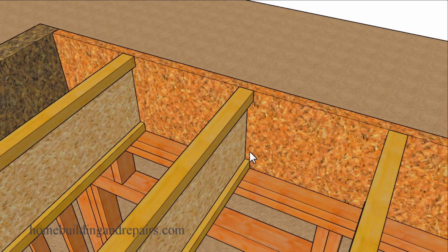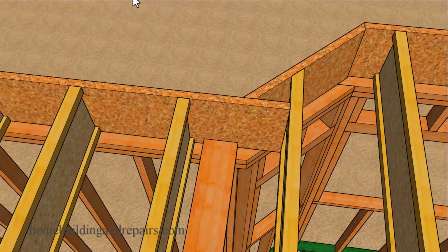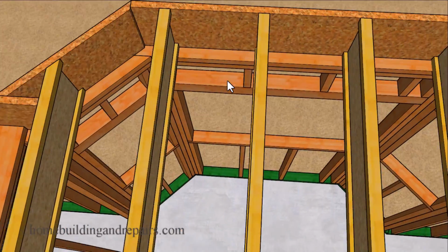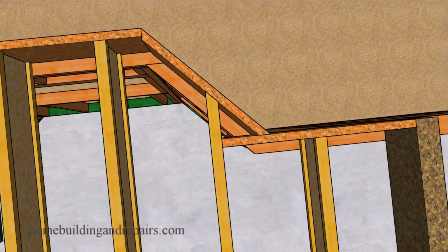And most truss joists will be fastened to the top framing plates with either 16D nails that might be commons or sinkers or even different sizes. Again, 16-inch on center layout. Another way that you can finish this section here would be to extend the rim joist and kind of use it as a block up to the next joist here. And again, that would be if the lumber lengths allow it. Same on the other side here.